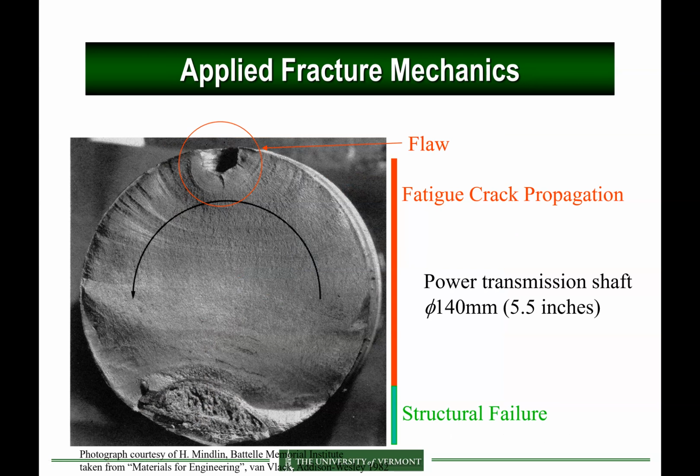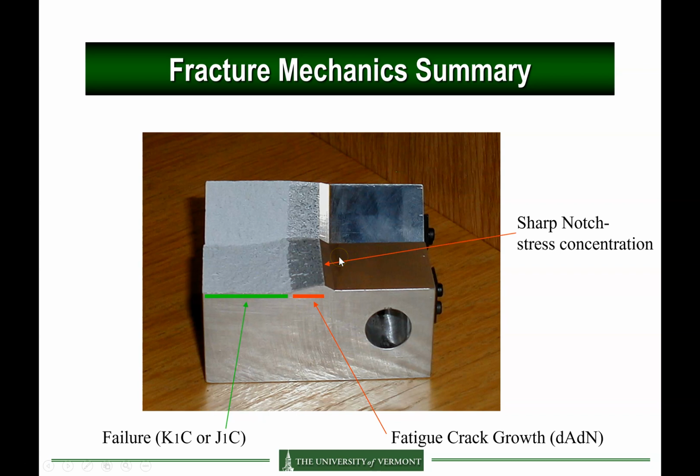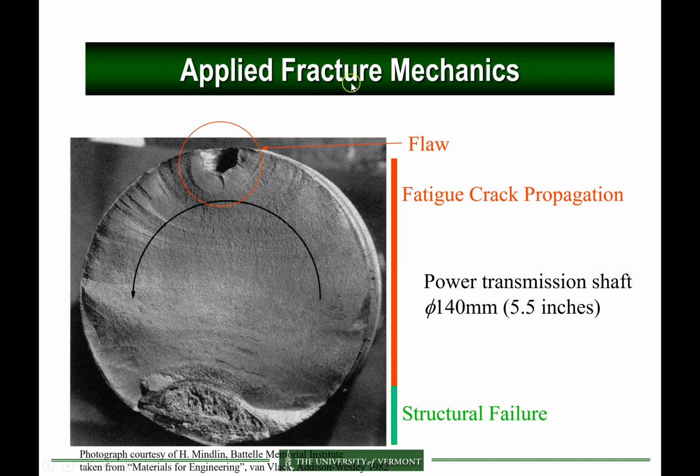And then how do you apply this data? Why this fracture toughness is important is because it's based on the stress intensity K, and K is truly independent of the structure. So basically, your fracture toughness in terms of stress intensity should be exactly the same regardless of the shape of your material or structure. So if we can establish it on the compact tension specimen accurately, then the same value should apply to any structure.